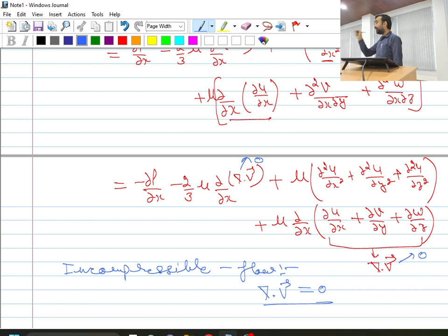Okay, so one very important point, while we have taken the Stokes hypothesis, we considered that lambda is equal to minus 2 by 3 mu. And I mentioned at that point that this particular assumption of lambda equal to minus 2 by 3 mu is applicable for majority of the flow situations except for extremely compressible flow situations where you are having the presence of shock wave, etc. There this hypothesis does not work well.